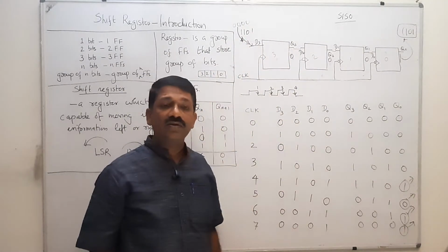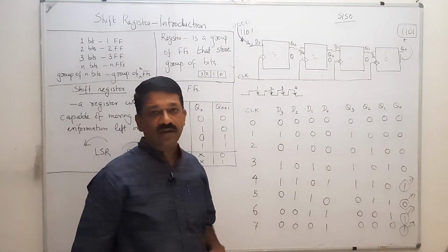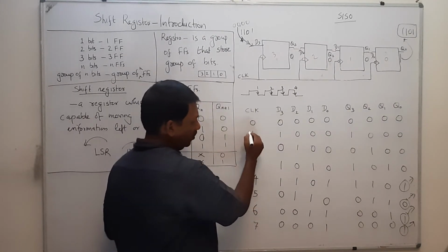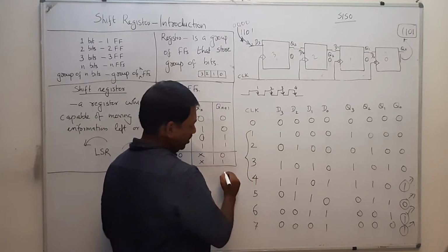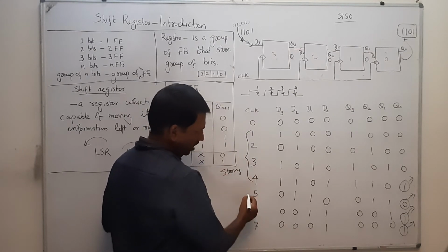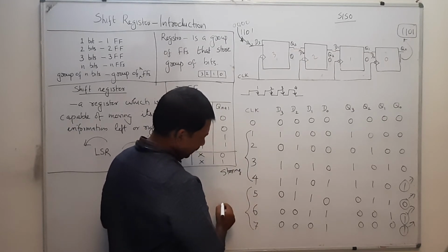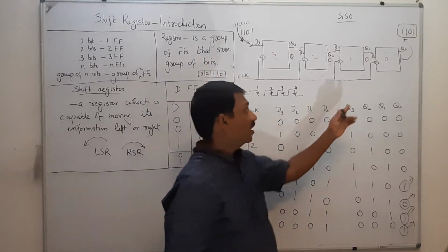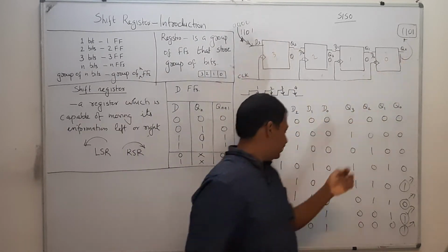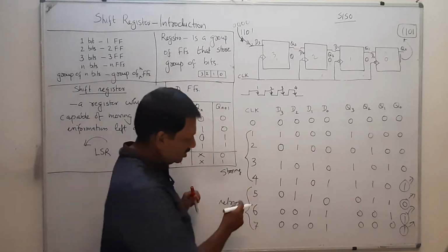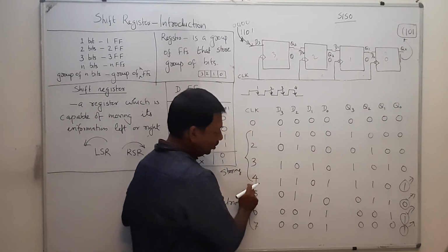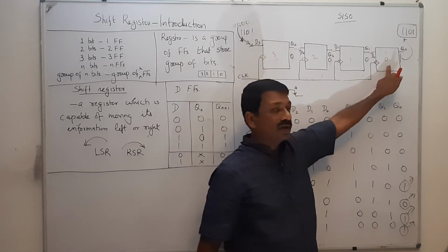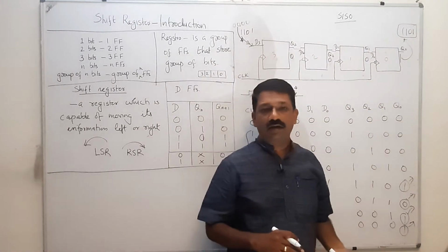into this set of 4 flip flops, and for the next 3 clock cycles, that means you took 4 clock pulses for storing and 3 clock pulses for retrieving. For retrieving the last one, that means in this phase itself, after this 4th clock pulse, the data stored in this last flip flop can be taken.